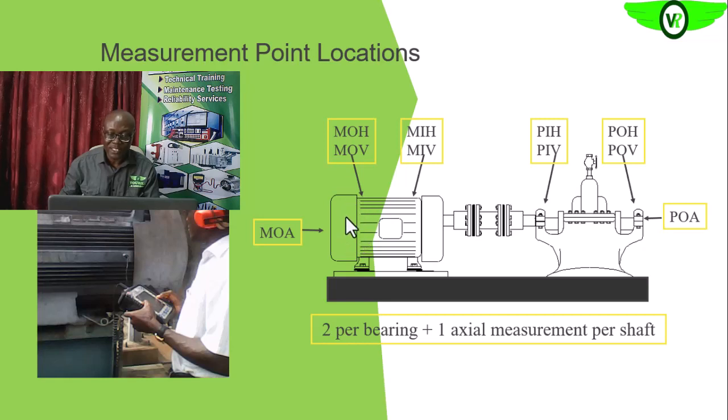let's say here, because this is the fan cover, we will not get much information here. Let's say here, that's the vertical position, and then here is the horizontal position. So the position that is axial to the shaft, in the same axis with the shaft, is called the axial direction. So we can look for any part of the motor that we can take such reading axially, and that will give us a reflection of what is happening around the bearing.